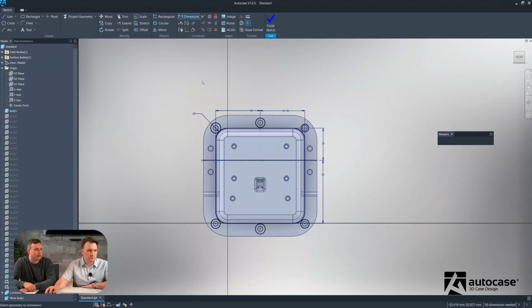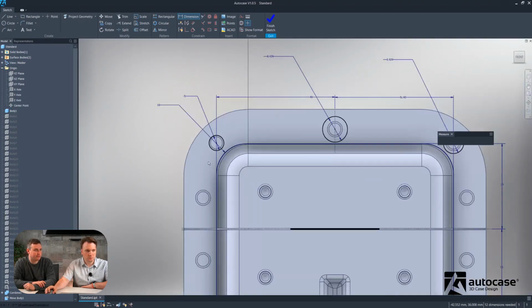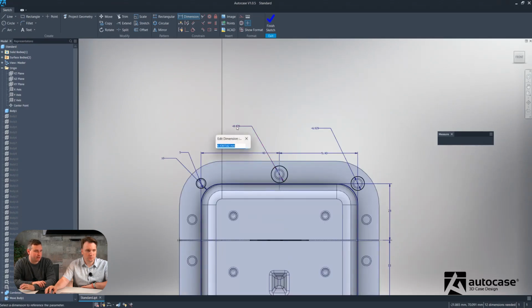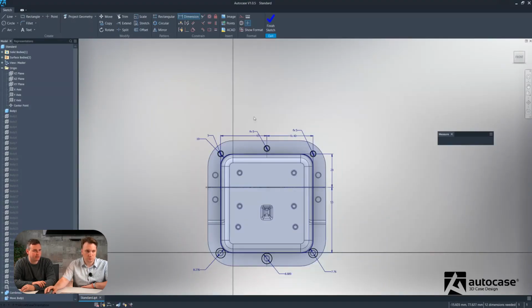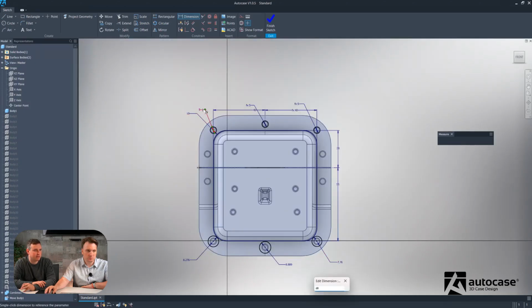So we can do that by simply dimensioning them, clicking on the circle, and then that will give us millimeter size. Go around and do that to all of them. One more to do. At this point, we'll set one of them as a master, essentially. We'll choose top left, make that 5 millimeters. And now using the same functionality of referencing each other's geometries, click on one, then click on the master one, enter, click on the next one, then click on the master.